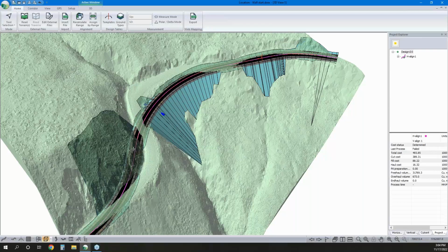So with this, our first section that we're going to deal with is our cut slope area here. So we're going to add in a cut retaining wall. So it'll be the pretty straightforward example. We've got this draw that we're going through, and we could absolutely add a wall in here, but in this case, we're going to go with a stacked rock fill. So it's still allowing us to fill material steeper than we could with the native material. And it's also going to have some erosion resistance if we have any issues with the creek.